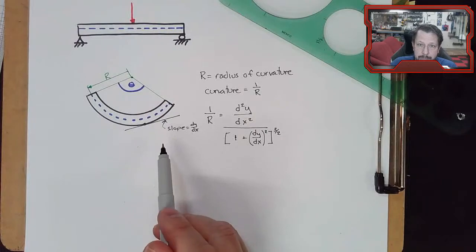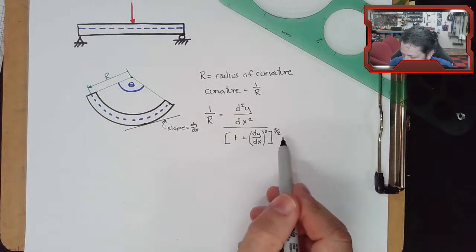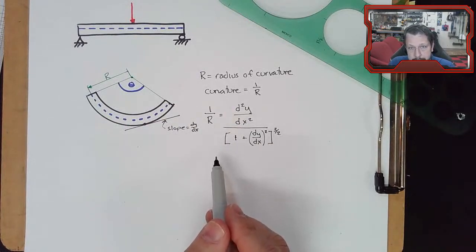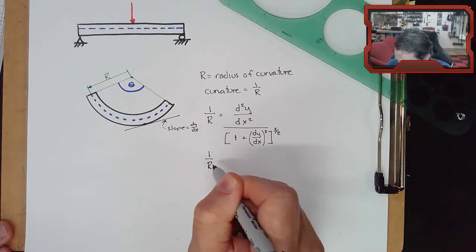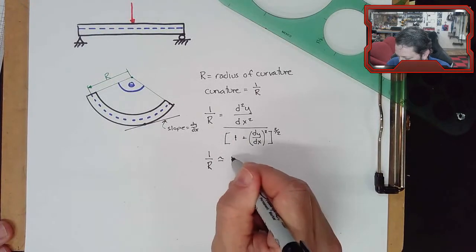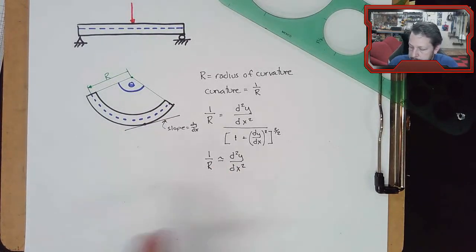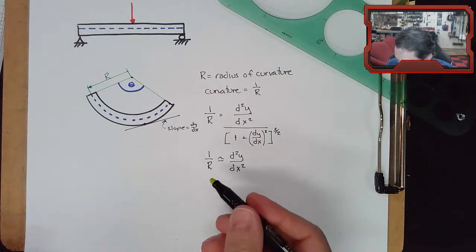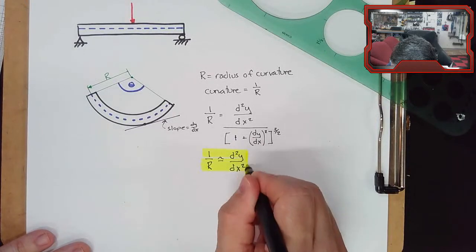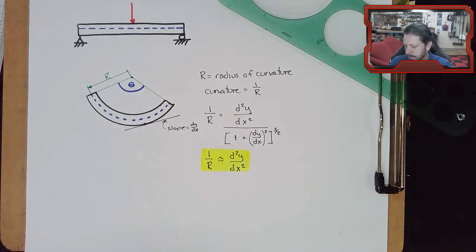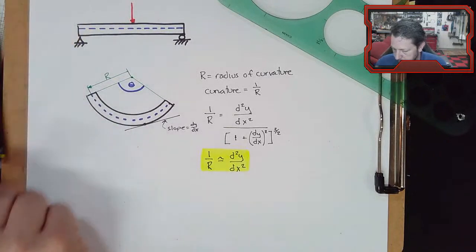In general, you want the beams that you're designing to not have a lot of curvature when they're put into service. So that's for beams in bending. This denominator is more or less 1, which makes 1 over r, that curvature term, pretty much just equal to the numerator. So that's good. That helps us a little bit. It doesn't tell us how to relate this to the load or the equation of the elastic curve, but it gets us some information that we can use later. So that's one thing. Now, let's go back over here.